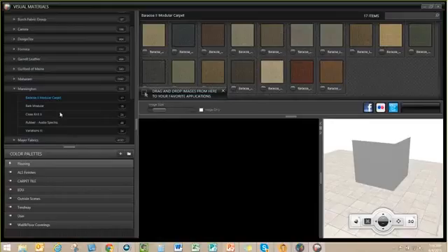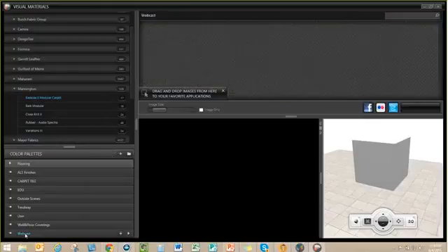But in this case, I want to be able to bring in my own finish. So down at the bottom, there's a series of color palettes. I have a handful already that I've used. I can also add a new palette if I wanted. If I click this plus mark, I'll just call this webcast. Now, realistically, you'd probably call it carpet tile or flooring or something that you're going to start putting additional finishes in this folder. So in the future, you can continue to reuse that carpet tile.